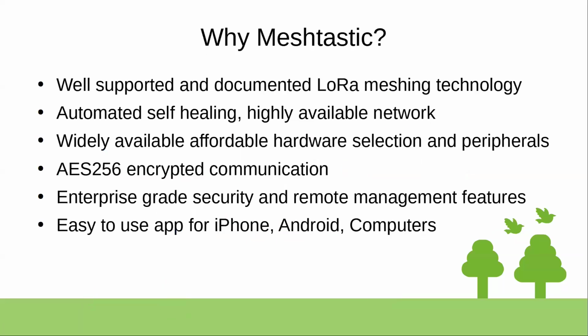So why Meshtastic? It is a well-supported and documented protocol. It uses the LoRa protocol, which works off of basically a flood routing method, so all the packets go in and then splash back out. Being a decentralized mesh, it's self-healing and highly available. The hardware is relatively affordable to very affordable, depending on which ones you get.